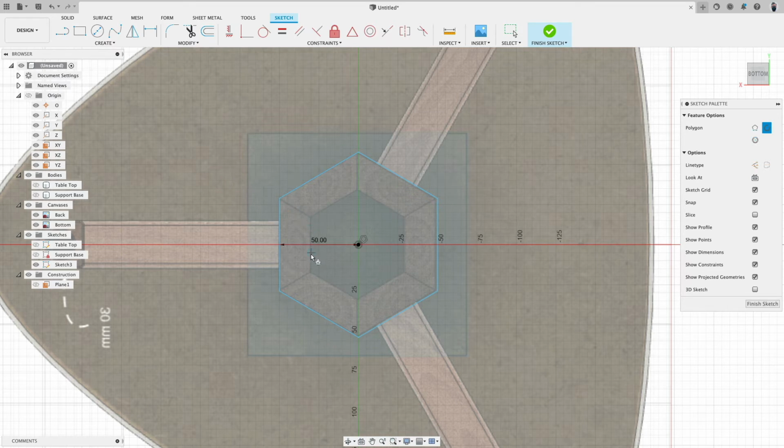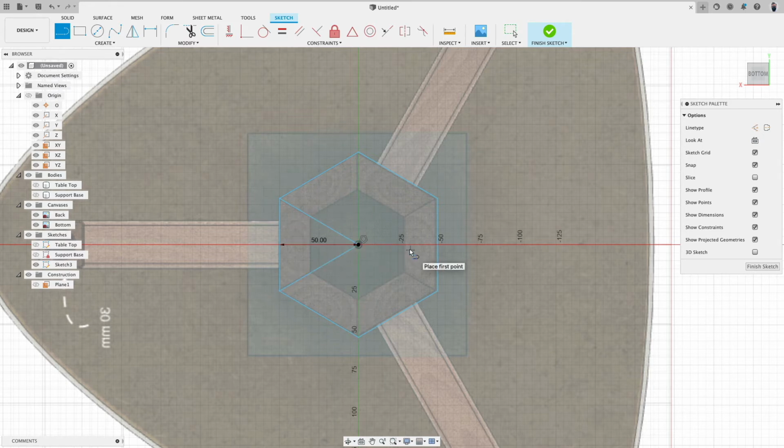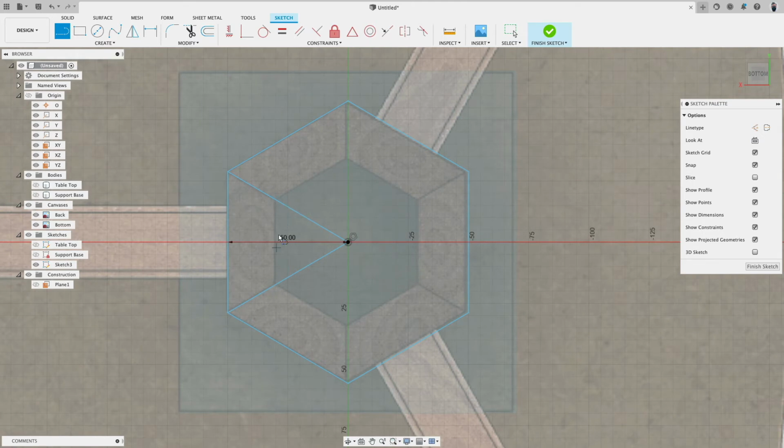Now I would like to create this. So from here into this corner and from there to that corner, 2 lines. Very good. How do we do this vertically? Super easy. I just, on purpose, again, be careful. There's somewhere in the midpoint. You don't want to click on the midpoint. So you click, and on purpose, I click on the midpoint here. Escape. And to change this, we can delete this triangle midpoint. And then this one again, we can drag onto that surface. Good. So this should be nice and vertical.